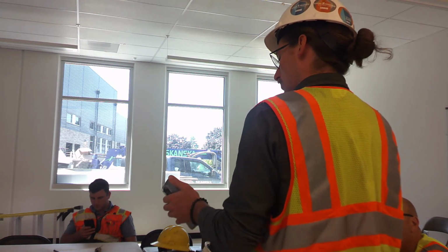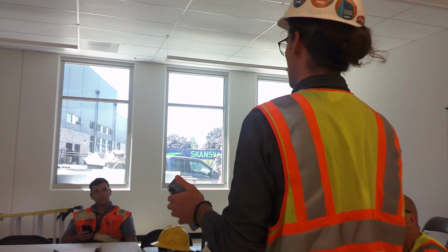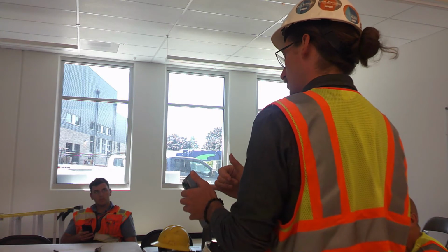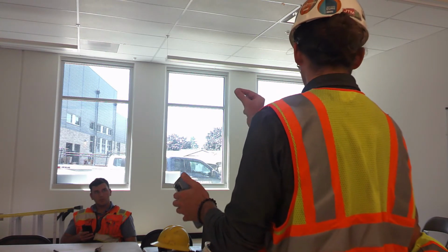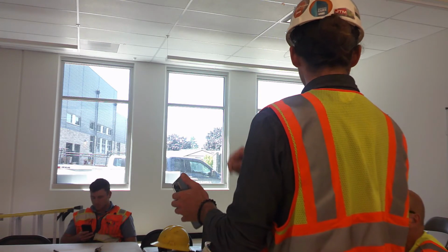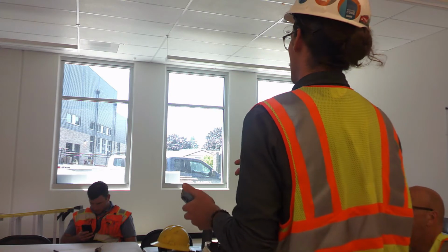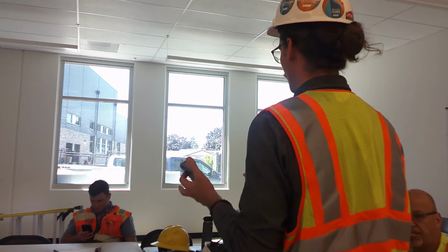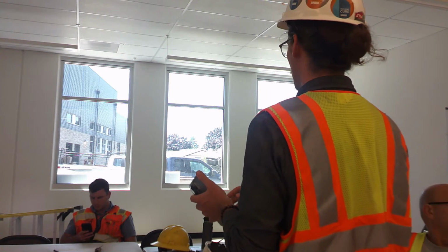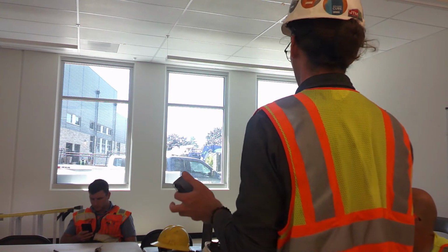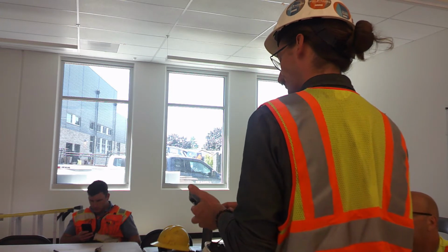So I'll go into the switches real quick, give that a quick overview. So we've got 3 6-button switches in here. They're all set up to do the same thing. You'll see it's got address 1, 2, and 4. That's showing what that little dial is set on. If you have them set on the same address, it just kind of creates like an undetermined state. Like you might see one of the switches show up, you might see none of them show up. It just kind of causes some issues for the controller to be able to talk to it.